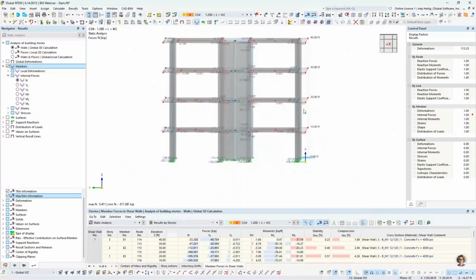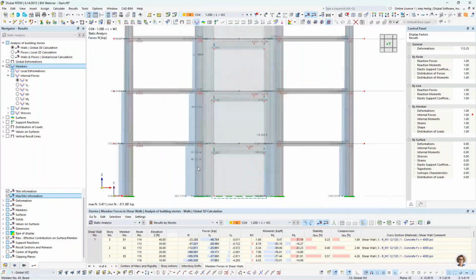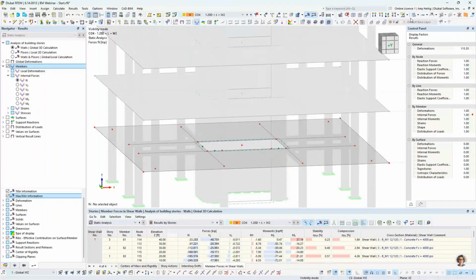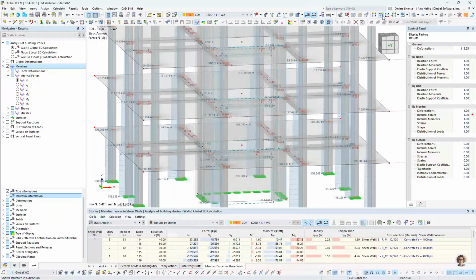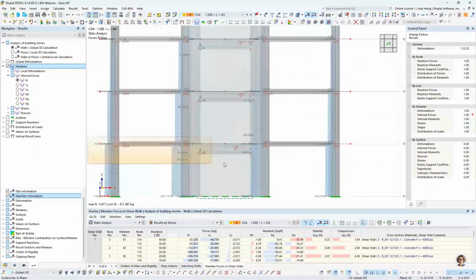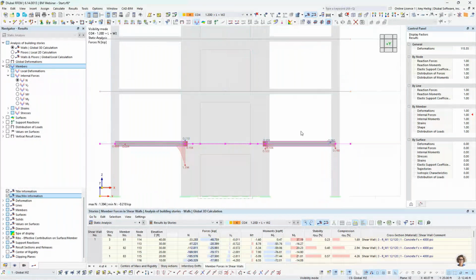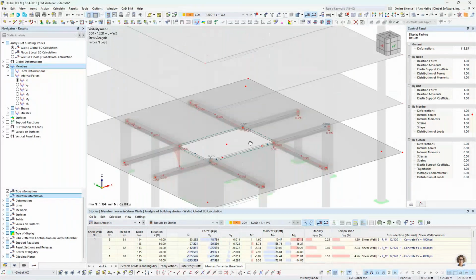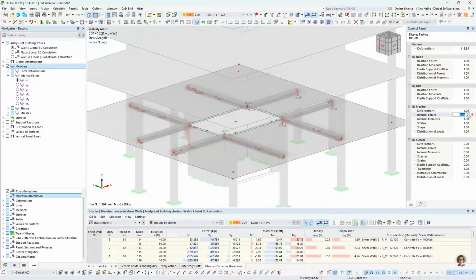I'm going to go ahead and try and create a visibility only based on my first floor. So looking at my first floor only, nope, I didn't capture my members. Give me 1 second. I want to capture both the floor as well as the members, but I'm trying to also not capture the deep beam. Okay, so looking at the visibility by the selected objects, you do have axial forces within these collector elements.